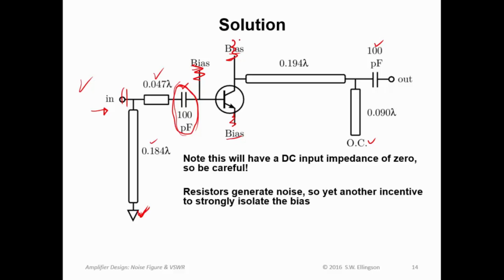For example, if you're using a resistor here, you may be required to put an inductor here. Well, if you have a sufficiently high frequency design, I'll point out this is 3.8 gigahertz, that inductor may be a huge problem. Right? So this is where a lot of the pain and effort in design goes, is trying to figure out how to combine now the bias with the RF.